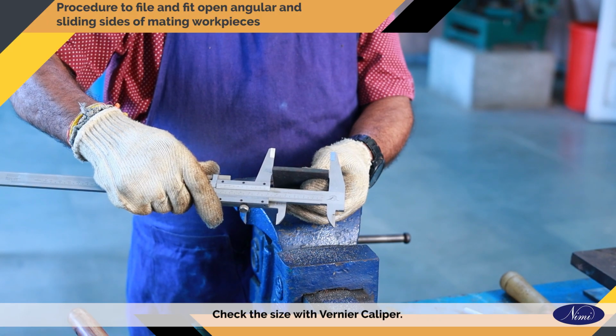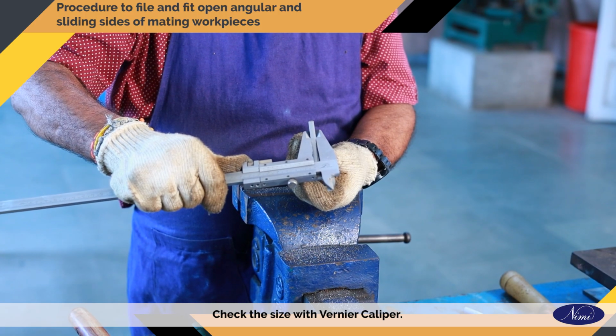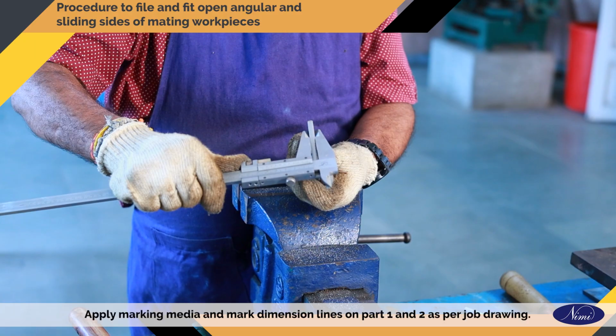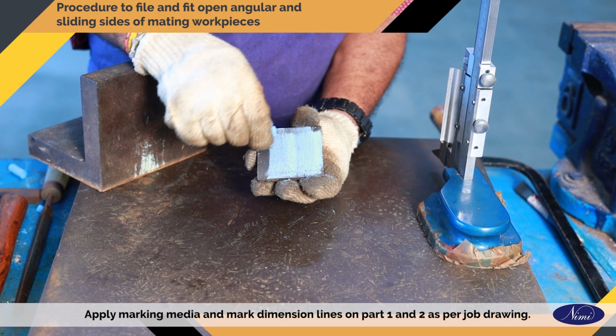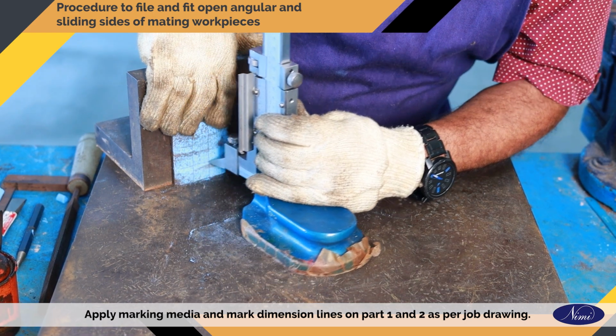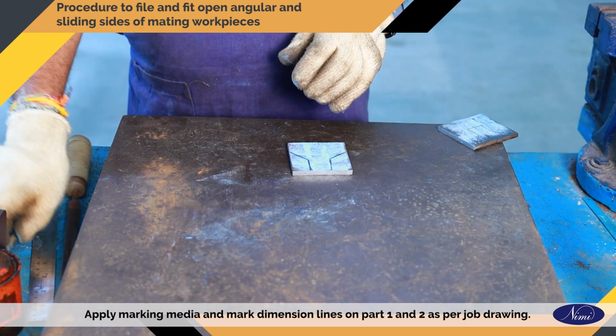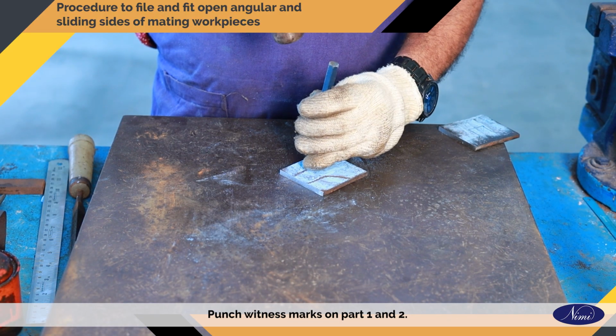Check the size with vernier caliper. Apply marking media and mark dimension lines on part 1 and 2 as per job drawing. Punch witness marks on part 1 and 2.